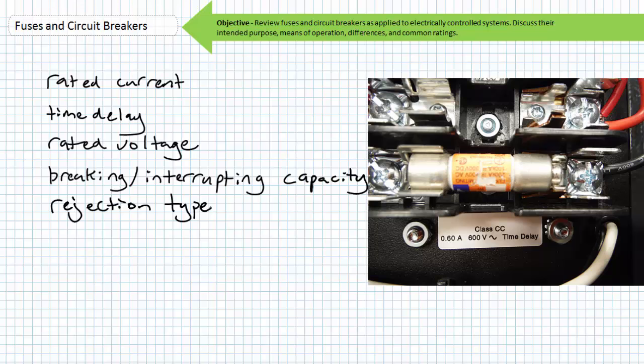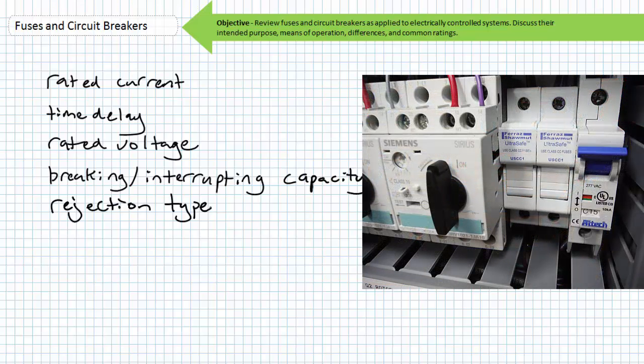Quick note about fuse holders. Do not open them while the system is operational. They're not intended to be on and off switches. Recall that even air can be considered a conductor between 2 high voltage points in close proximity. A purposely designed means of disconnection accounts for this possibility by providing a means of quickly extinguishing any arc that may form between the 2 points. As we'll learn later, circuit breakers designed for this purpose employ some pretty exotic means of doing so.